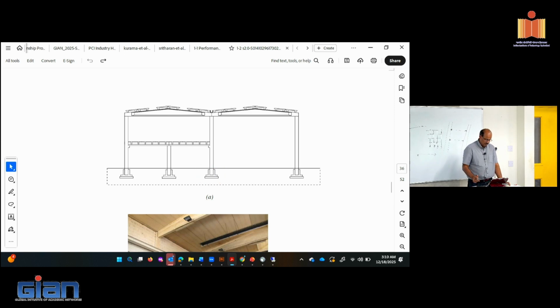So you could see how they assemble this structure. Double T's are used here. You can see they use corbels here where it's supported. And in this area, the roof is also kind of a tapered precast beam that they used.